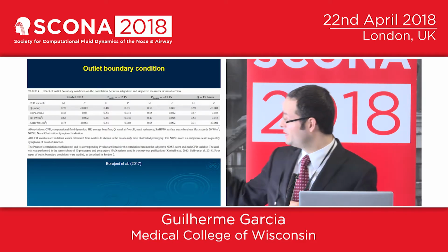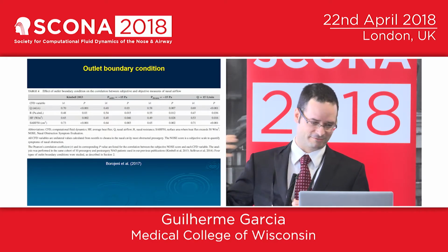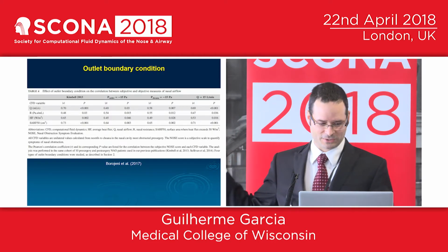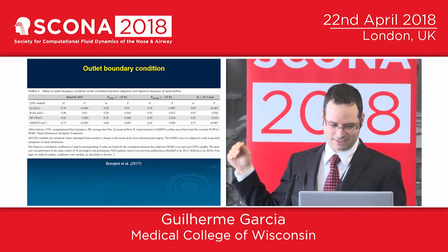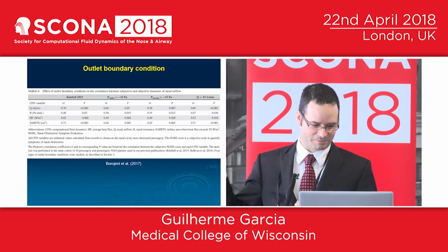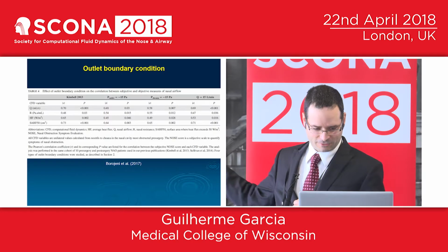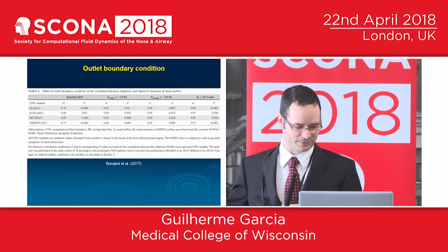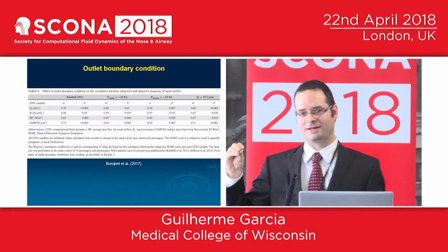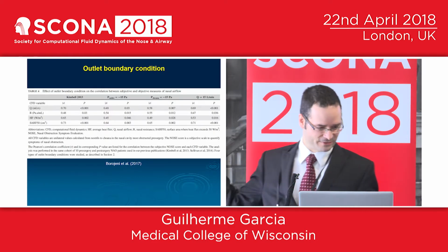And we compared the Kimball 2013 paper boundary conditions, which used a patient-specific flow rate estimated from body mass, versus setting an outlet boundary condition of minus 15 Pascal, versus changing the outlet pressure to have 15 Pascal at the end of the septum, and versus the 15 liters per minute boundary condition at the rightmost side. And we quantified the correlation of patient-specific measures, such as the NOSE scale, with these various CFD variables like